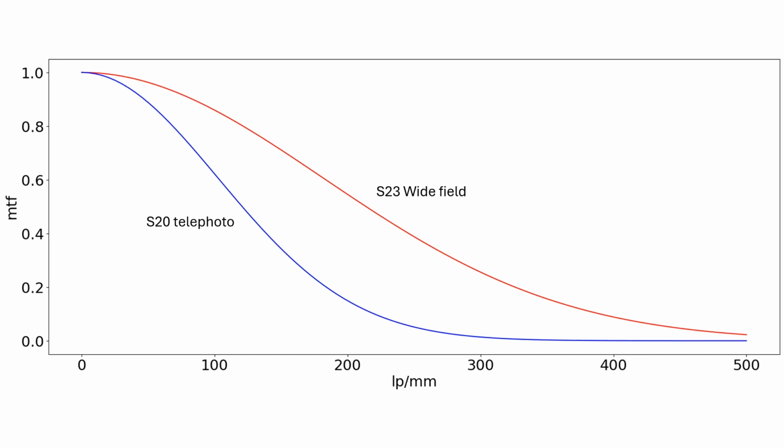So even though the wide field is a shorter focal length lens, it has much sharper images on the sensor than the telephoto, which is typical because as you make a longer focal length lens and fold it into a camera, you're going to get a larger F number, which in the case of the telephoto here is quoted at f3, whereas the wide field is an f2 lens.